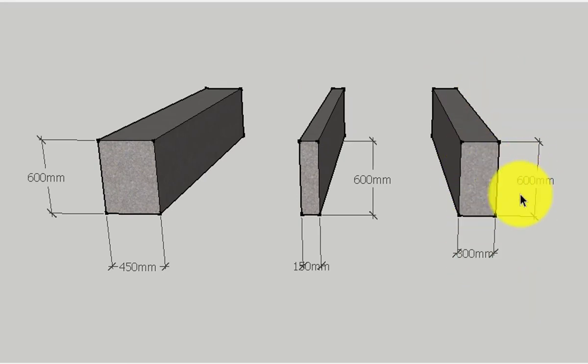You can see the dimension of the cross section is 300 mm by 600 mm. So I can say the cross section is appreciable, therefore it is not uneconomical and it is durable. So it makes a blend between the working stress method and the load factor method. That is why the limit state method is the most appreciable design method. Remember that a high cross section is uneconomical because it takes a lot of concrete to cast it.